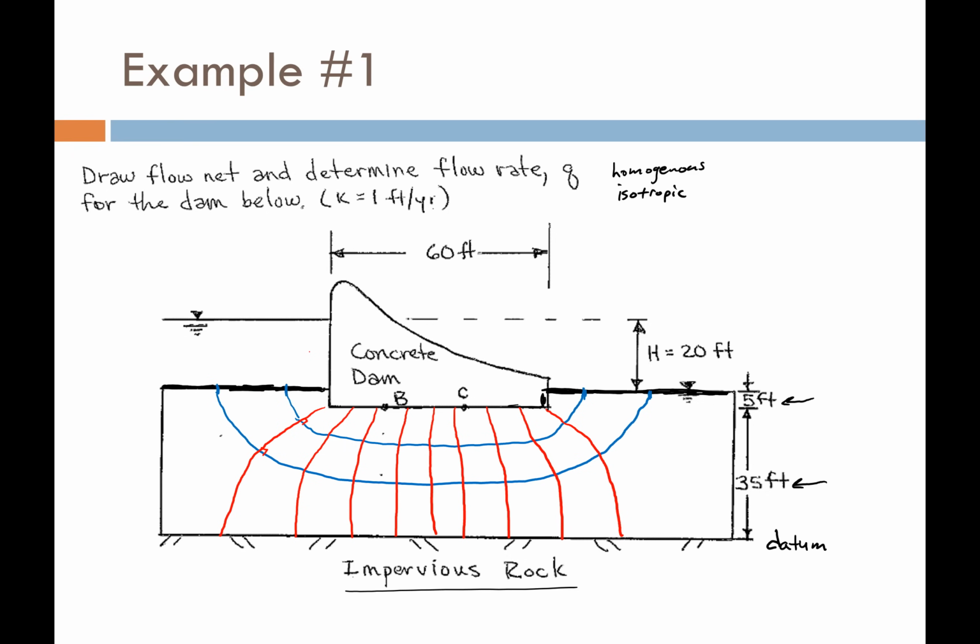So let's count how many equipotential lines I have between my first, so this is my first line, the ground surface, and this one here is my last. So I highlighted those in black just so I know. So how many equipotential lines to get from, say, if I have this dot and I want to move it all the way to the last equipotential line. So 1, 2, 3, 4, 5, 6, 7.